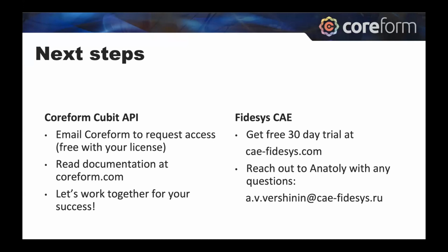It's much more common that it's used as a consumer, where if you've got a specific geometry that you need for like an ASME standard test, typically you build those in a CAD tool and then you import those into Cubit for meshing. That's typically the workflow. We do have on our roadmap to improve Cubit in that area, but that's certainly not a standard workflow yet in Cubit.